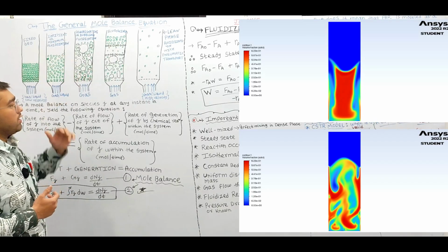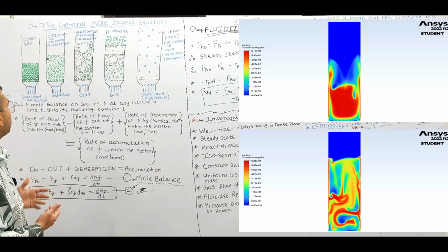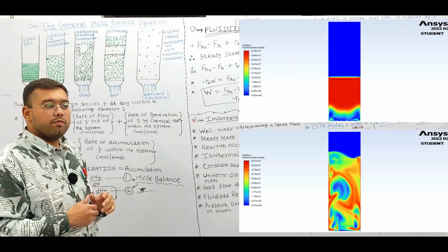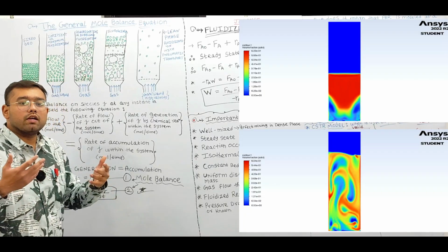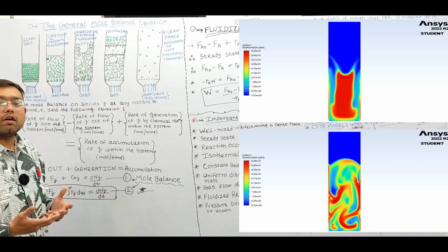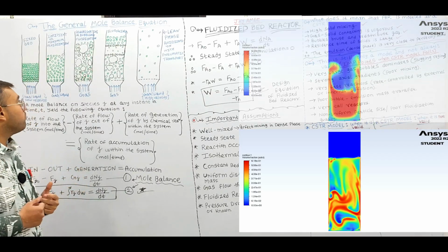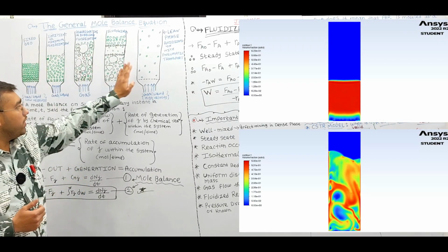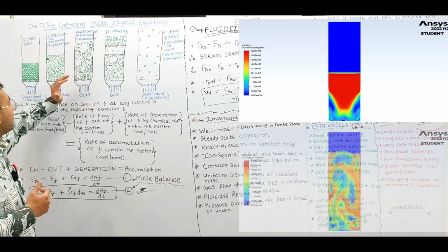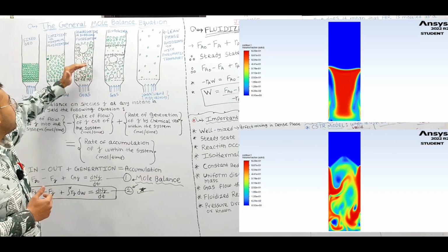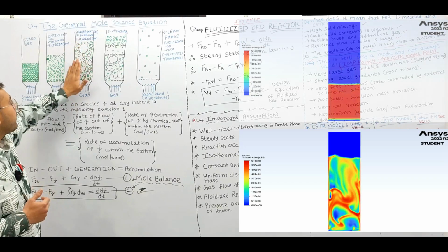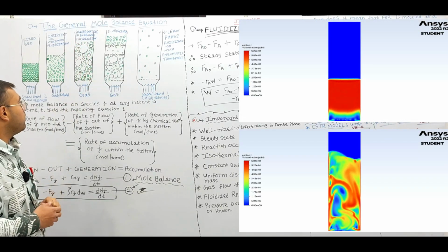The catalyst bed becomes fluidized. So in many operating regimes, where the term operating regimes means a set of specific conditions or operating parameters under which a system or a process is functioning, the particle and the gas motions give a very good mixing of the solid plus gas in the entire emulsion phase of the fluidized bed reactor, right?